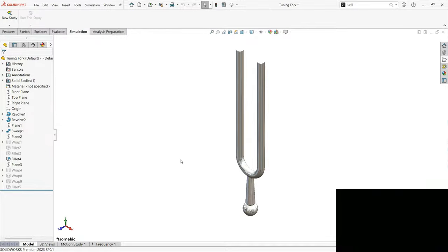So how we can run the basic structure analysis and the modal analysis to predict the basic mechanism of it and the resonant frequency and the mode shape of it. And in the basic structure analysis, we had gone through all the basic steps to cover the structure analysis and meshing and the material application, and also the design changes required and the stress hotspot and factor of safety also, and how we need to improvise and optimize the model.